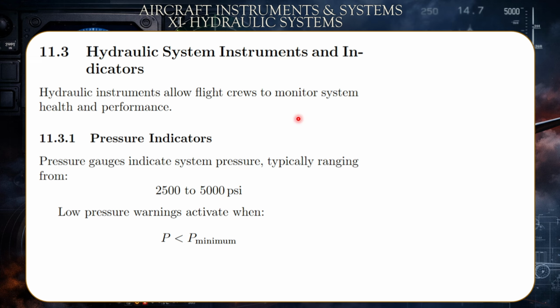Now the pressure sensor can be a capacitor, for example, that would change based on the pressure value. It would change its own capacitance based on the pressure, which in its turn alters the area between the two armatures, between which the electric field exists. So by altering that area, the entire capacitance value would change, and this would be translated into the current value of the pressure.